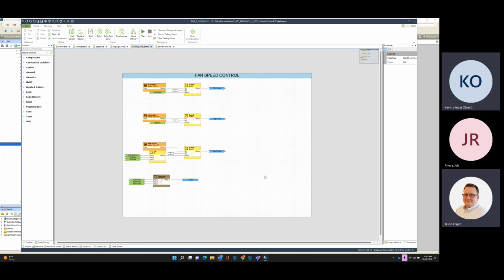So we had just spent an egregious amount of time going back and tuning these current switches, trying to dial them in. I can't even tell you how much time it's been. And so I went back to the engineer and everybody else. I'm like, hey, don't ever design a project like this again and not use anything other than a current transducer where you actually read the amps. I don't care if it's 0.8 amps. Don't let them do this to your buildings again, right?